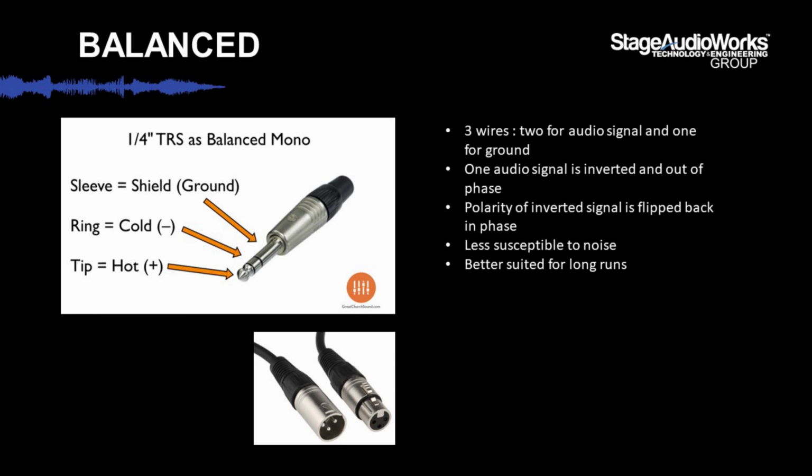As long as the cable is high quality, there isn't much of a difference between these. And by extension, you could even use the 3-wire signal for an unbalanced one. You can just link the 2 cores together inside. So a lot of the time we actually just take 1 type of cable to a job because it can carry both a balanced and an unbalanced signal.